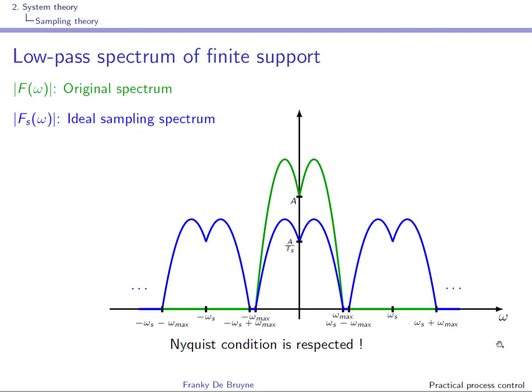You have to understand this slide, and you have to be able to apply it to the sampling of a sinusoidal type signal, so that you can compute at which frequency the sinusoidal signal will present itself as a low frequency alias when the Nyquist condition is not met.